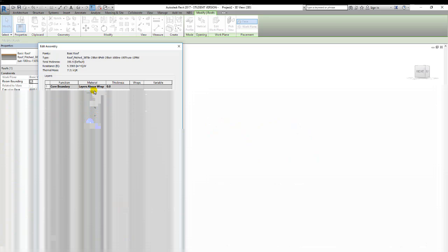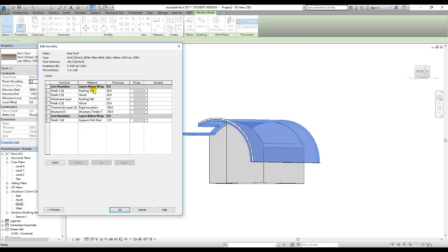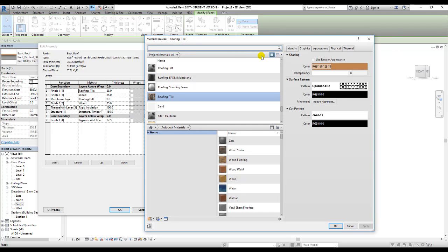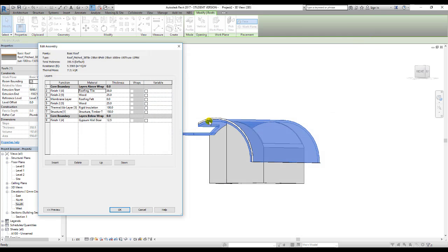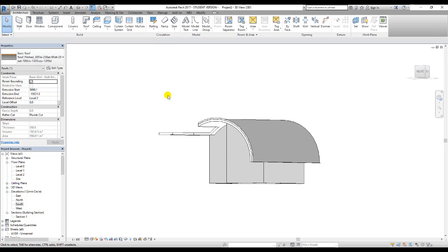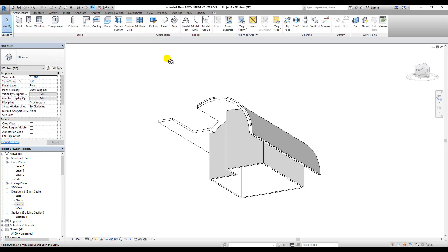Okay, so roofing tile there, but you could have a roof slab, or not a roof slab, but a floor slab, a floor tile, on a bed of gravel, on then some bitumen felt, or some one layer system and insulation, all that sort of stuff underneath it. But then you just have to make sure that you changed the materials to suit, okay, to make it look like a roofing thing as opposed to a roofing tile. So hopefully you've got the picture on how to create roofs.